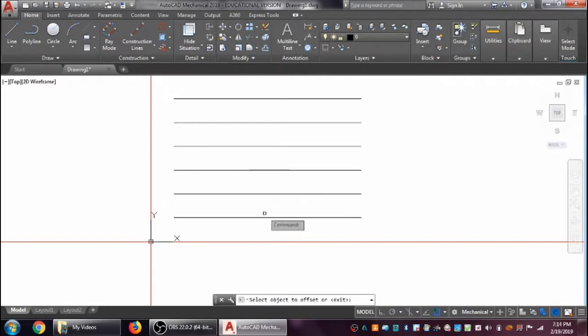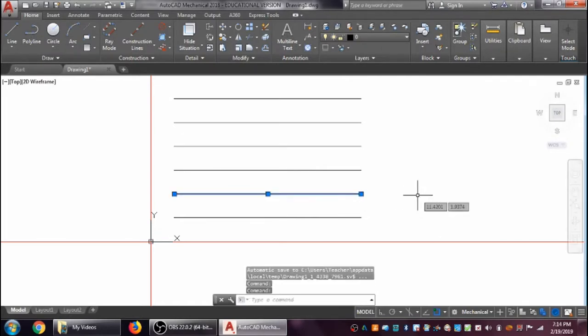So here, if I come down, I'm going to leave the first line, the one that we started at x1, y1, as an object line. And I'm going to go to the next one up, and I'm going to highlight and click that. Hang on, I'm still kind of in here, so we'll just hit escape to back out. And then you can click, and when you get that, you should get your object snaps there. I've got object snaps set right now where it shows the endpoint here and the midpoint.